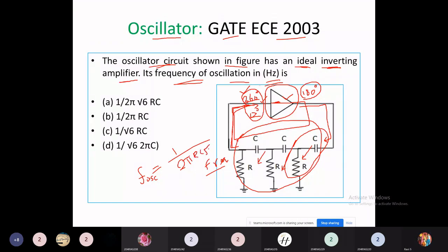Right? There is a big length of derivation that we can achieve through simplifying this RC network one by one. And finally, we obtain the expression for beta, where beta is nothing but the output of the amplifier is the input for the feedback network, beta, right? And this is the input to the amplifier, which is nothing but the output of the feedback network.